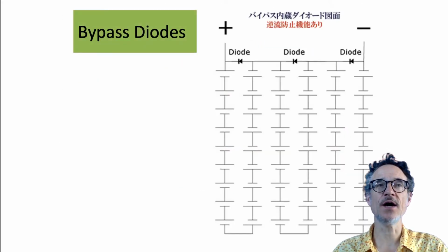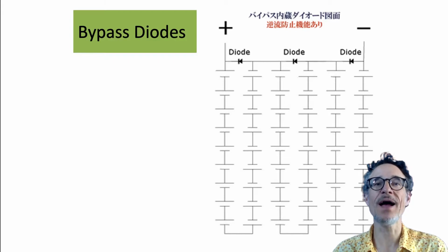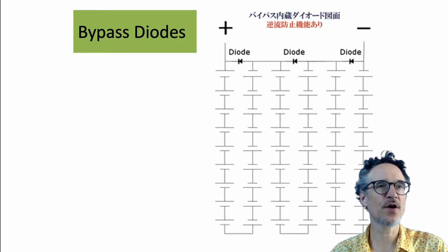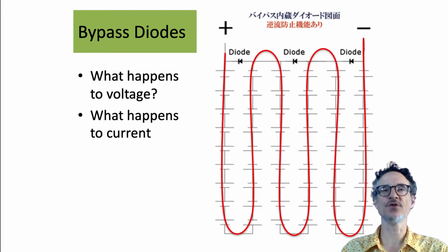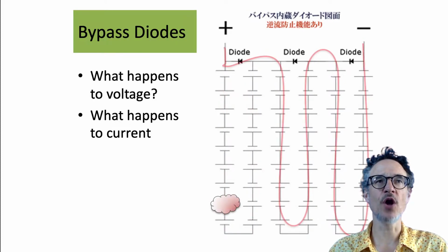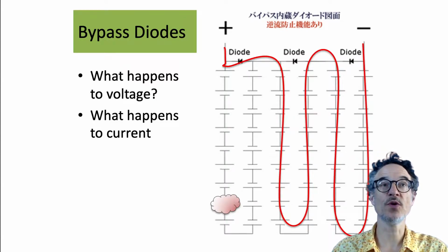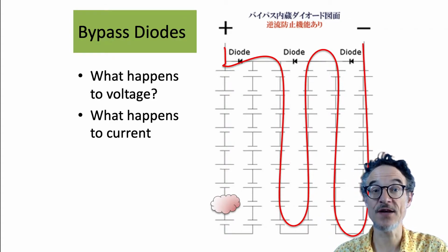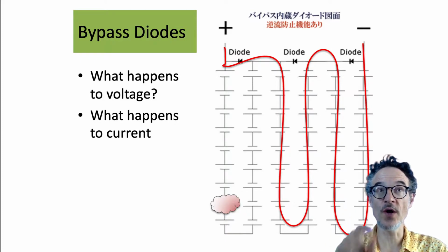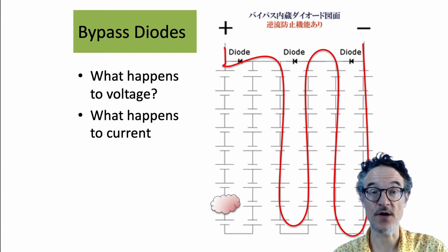And what happens then, often inside a solar module where you have many different cells together, you have what's called a bypass diode. So in a normal situation the electricity is going through this way, but if you get something blocked, then the whole of that section of cells will stop producing electricity and it will be diverted. But the others can still produce electricity. If not, then stopping current in one cell could stop the whole of your panel from working if you don't have these bypass diodes.